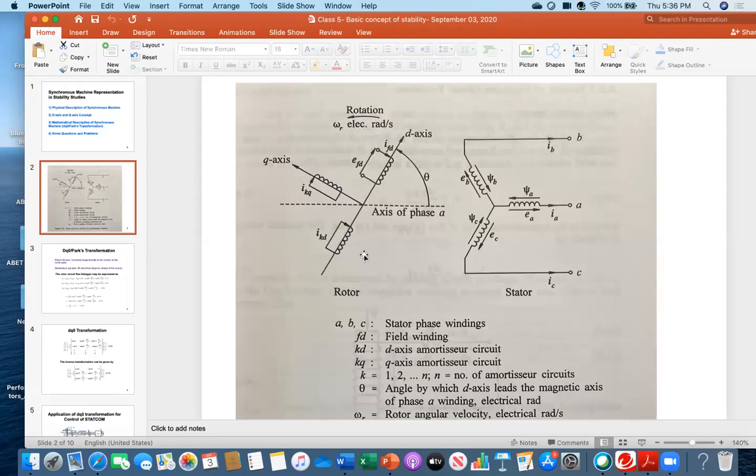Can you remember that I mentioned synchronous machines have damper winding? I think I discussed for a synchronous motor that without damper winding, it can't start. But damper windings are used in synchronous generators also in order to eliminate the hunting effect.